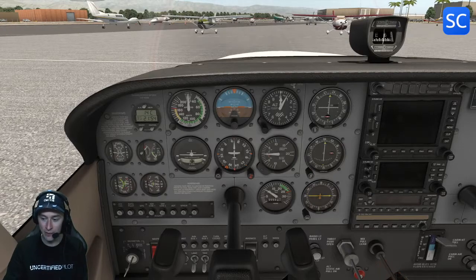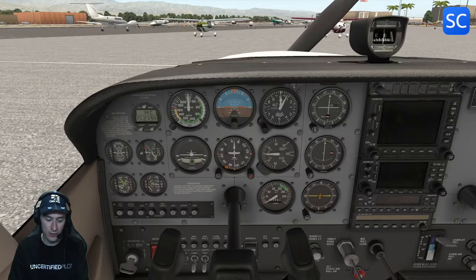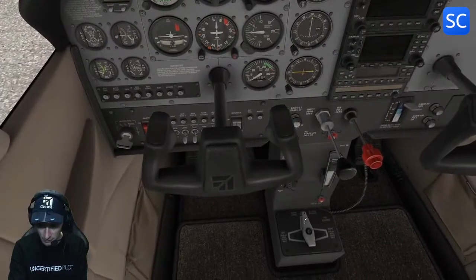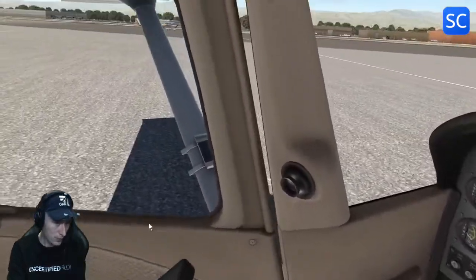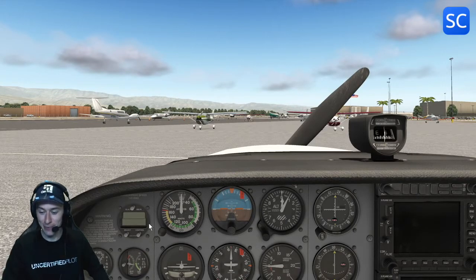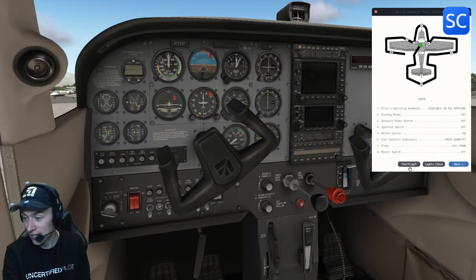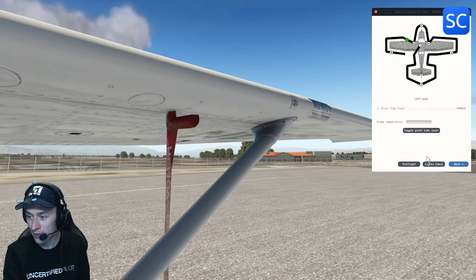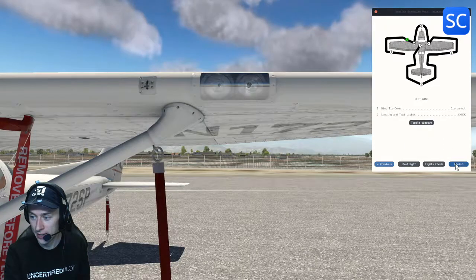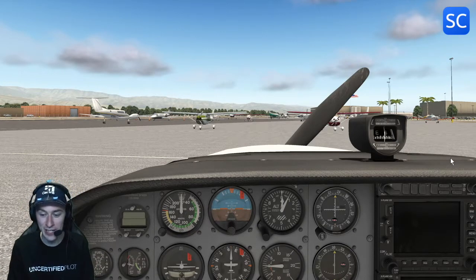So, avionics are off, cut off, burn every little fuel there in the cylinders, then turn off the spark plugs and then the batteries. Parking brakes are set, prevent cross-feeding, open the door, and there we are. Release our real seat belts here in my freaking nerd chair, and let's also do our proper post-flight checks. Post-flights, for example, the pitot tube cover, the tie-down, this tie-down, that tie-down, and we are finished. And that completes our demonstration of the Reality Extension Pack.